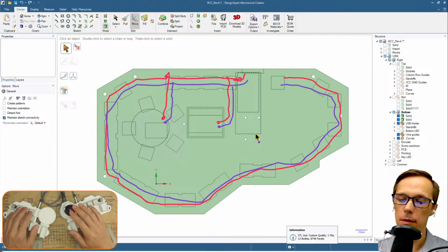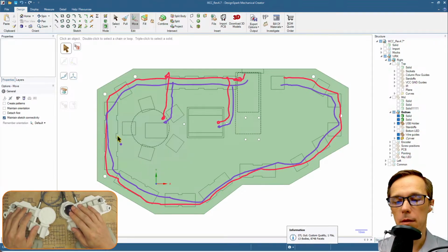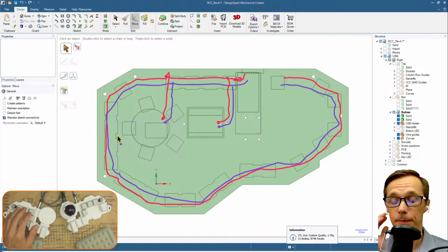Okay, what else? We don't need resistors anymore because we won't be using I2C to connect the parts. We'll be using serial, and this way we don't need to mess with the I2C resistor, so that's okay. Less stuff, but we're going to be needing resistors over here. So much stuff.